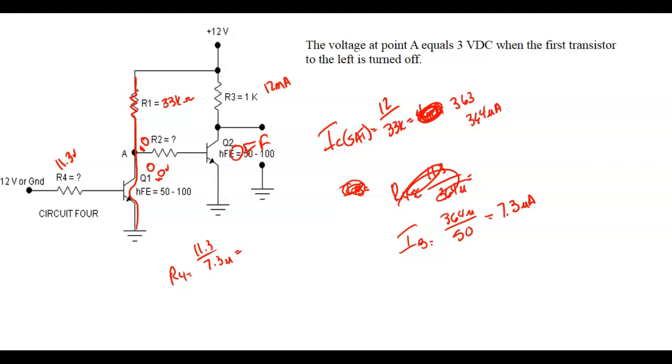You grab a little thing with one hand, just twist it, right? Like our sinks down here, we can just flip the little handle up and down because you get that mechanical advantage. But what we're doing here is getting an electrical advantage. A very small base current can control a proportionally larger collector current. So whatever that calculates out, that's okay. About 7.3 microamps is controlling 12 milliamps.